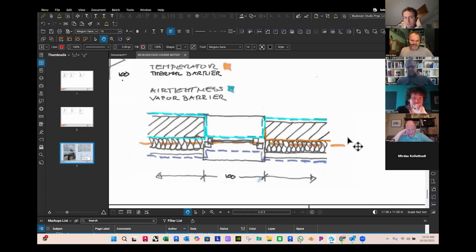So therefore, if you're only dealing with a punched window facade in a concrete building, then you only need a little tape that covers the edge or from the inside. That's it. If you have a skeleton structure, classical wood timber structure, which has to use a film on the inside and also tape all around to make sure that no vapor is coming out, then that's an actual product.